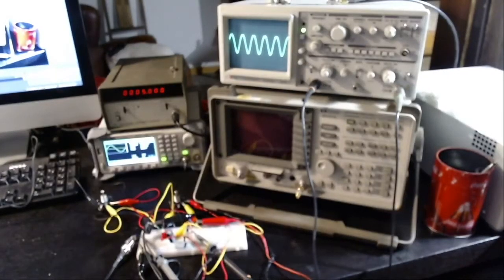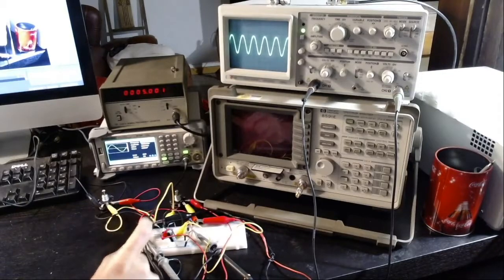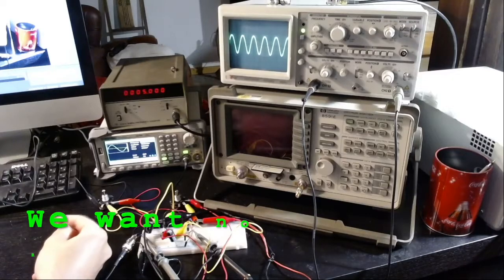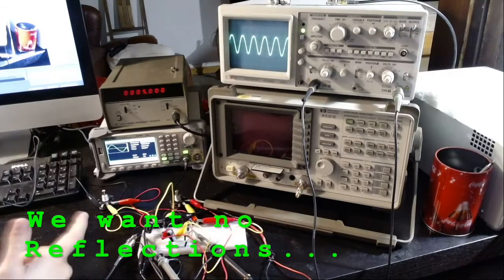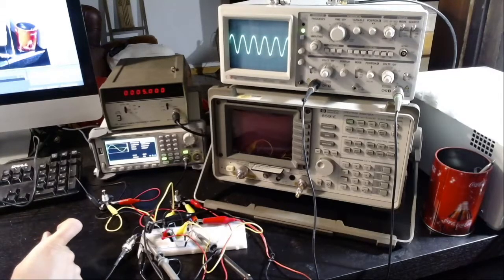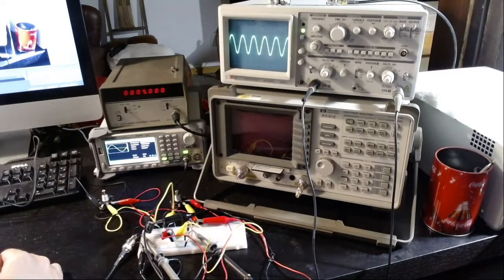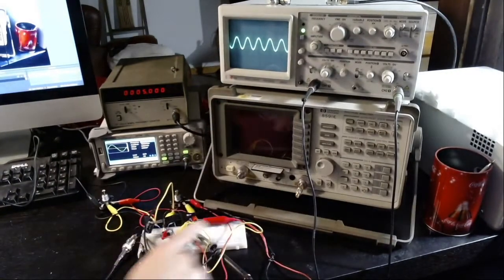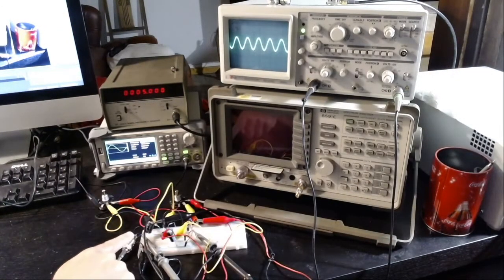And the third and last specification was that this amplifier has to have a precise 50 ohm input impedance. In other words, we don't want any rejected frequency back to the mixer or to the signal generator in this case. This was a requirement of the specific mixer I was using, and to work well, it doesn't really want any reflections. And so to see that this is the case, let me switch to just the input. So that's channel 2 here looking at the input.